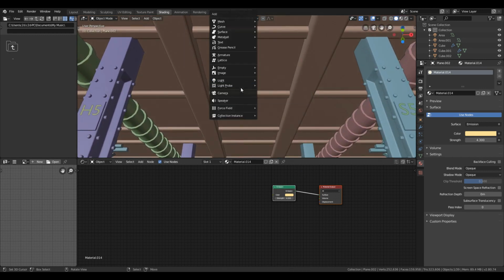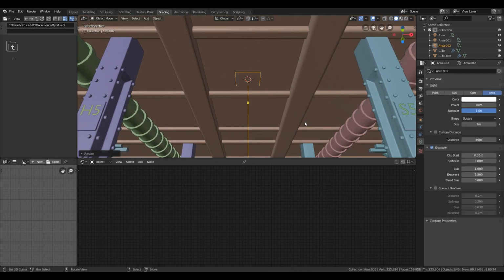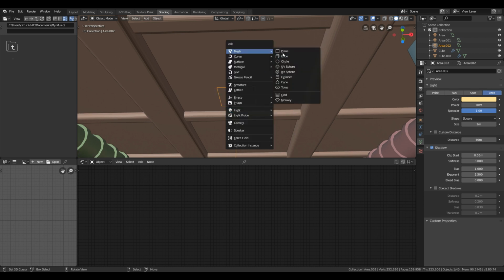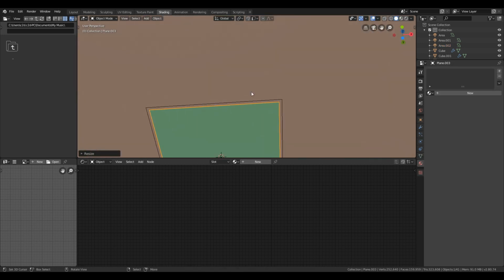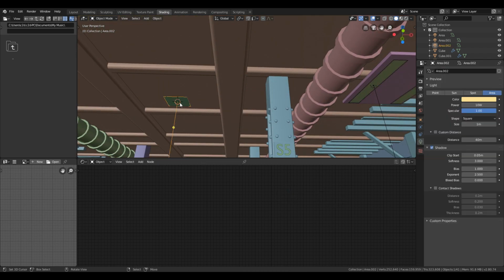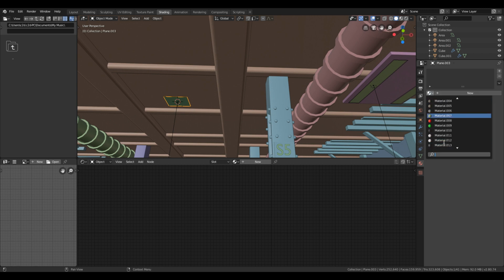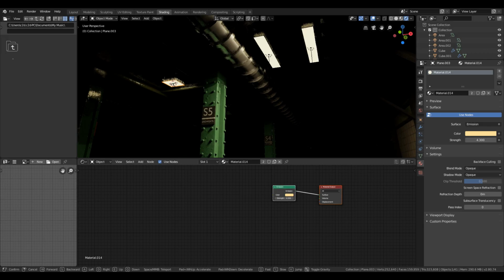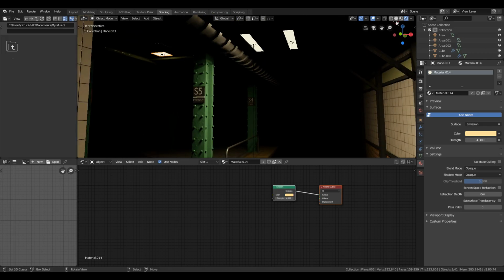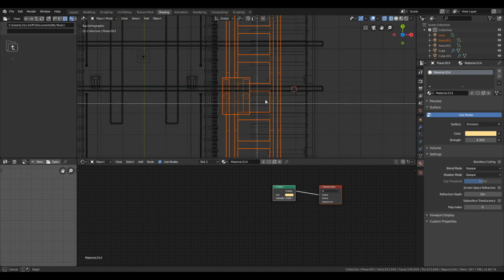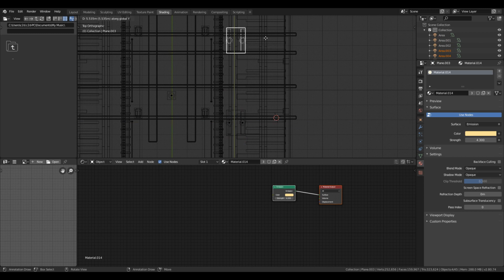In the same manner, move to the center of the platform and use area lights with a scaling of 0.55 and do the same procedure with it, but leave the strength of the light at 10. Now just duplicate the lights and their light source after every pillar.